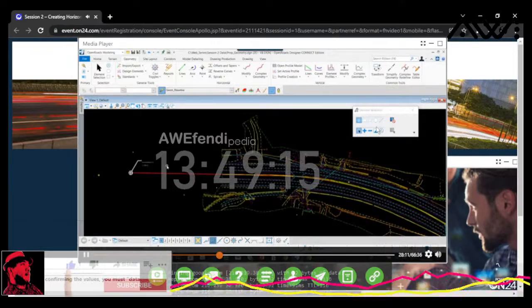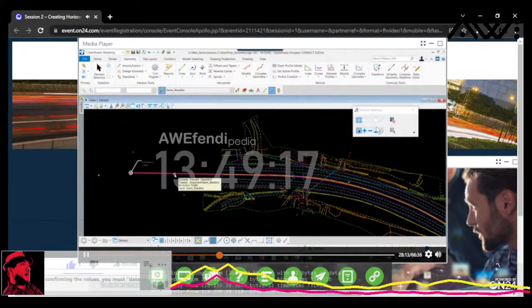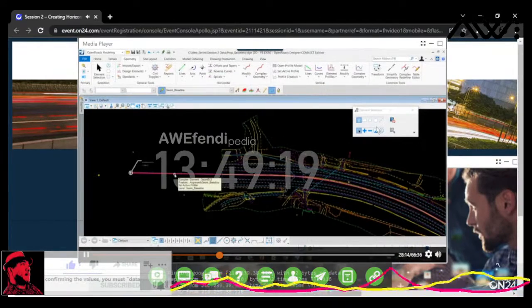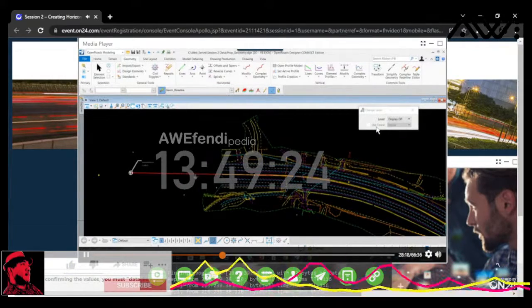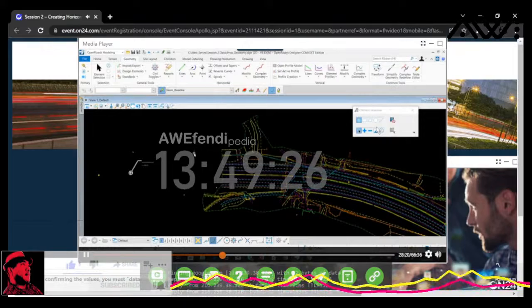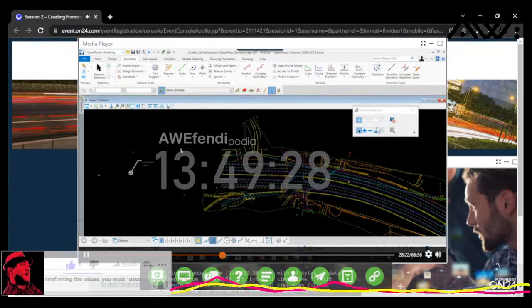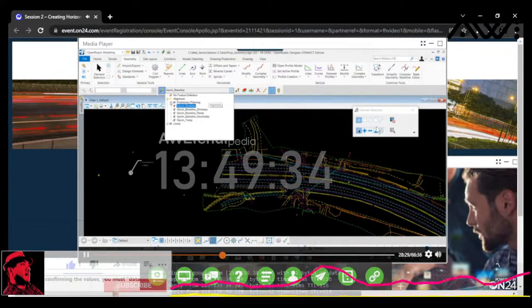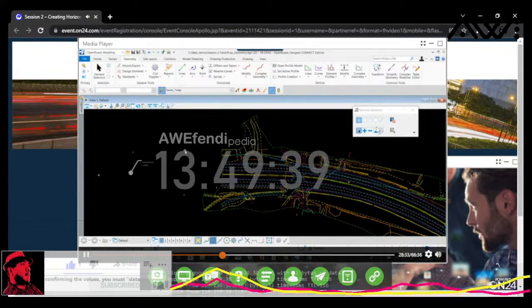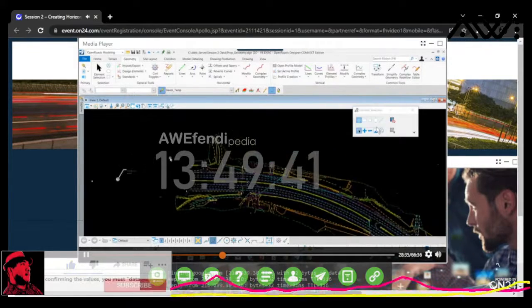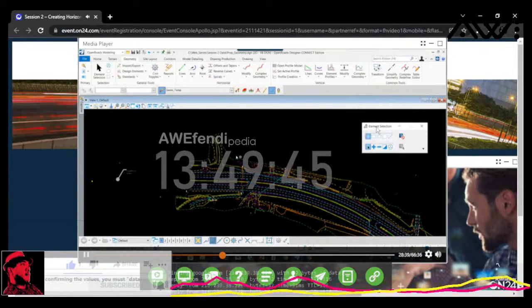So I'm going to turn this particular horizontal off, and I'm just going to turn it off by level. All right, so it's there, it still exists. I just turned the level off behind the scenes. And to create this secondary baseline, I'm going to change my feature definition to temp. Okay, so this secondary alignment we're about to build, I just want to do this to expose you to another method if you'd like to use a tabular workflow to create this horizontal alignment.